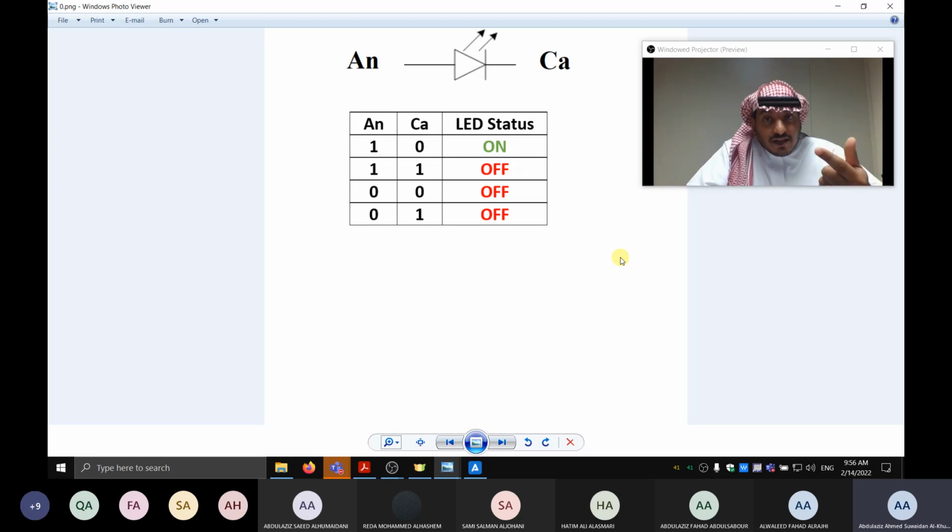Because if you put the voltage directly on the diode itself, what will happen? The internal resistance of the diode is very, very small, which means the current will be extremely high and it will burn out instantaneously if you connect it directly to the voltage source. So you have to have some resistor to limit the current and protect the diode. Please understand that, so don't burn the LEDs in the future. Put a resistor to it. This is all external information, extra information.